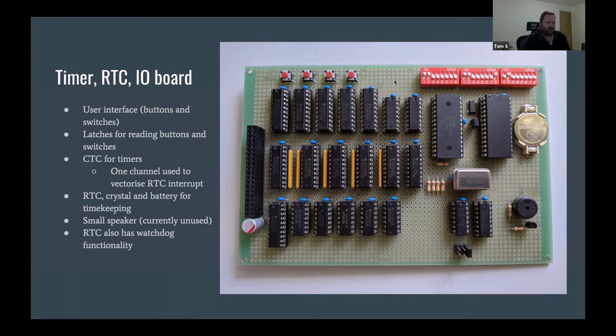There's actually a little 4-position switch that's missing from the top row there, which I added in, and that allows me to change a couple of little options, like how much dimming I want to have, like 25% versus 50% duty cycle or something like that. And I think there's a couple of other little options that you can select using that. But yeah,